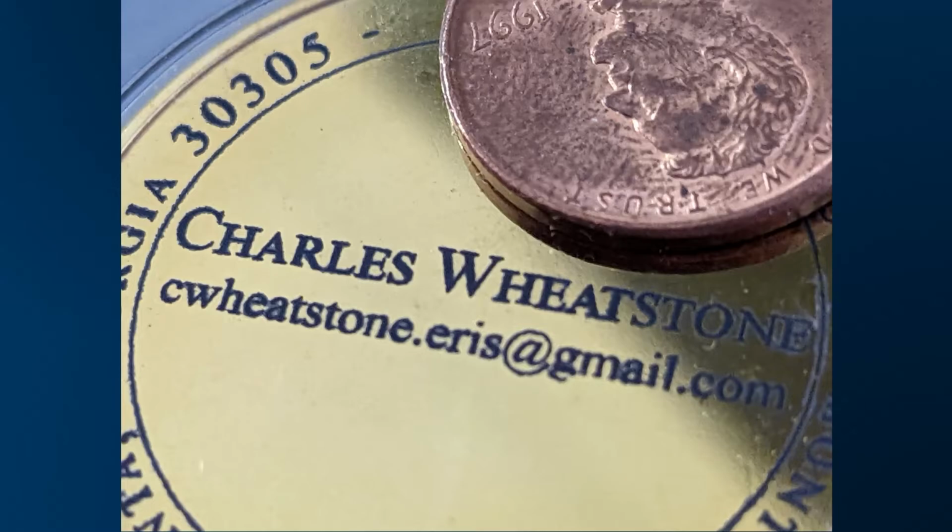How this is done is they make commercial sprays, and there's a few do-it-yourself ways you can do this too, but they make commercial sprays that you spray a metal with, and then you laser it. Everywhere the laser touches, the material that you sprayed on melts, and it bonds with the metal. Then when you're done lasering everything, you take it out and you wash it. The areas that were lasered are stuck to the metal, so they will remain. The areas that were not lasered are completely unbound, and so they wash right off. And so that's what you see here.